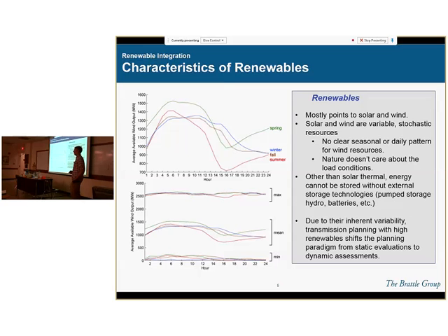And so when we don't have a lot of wind, the load shapes and the load we face are relatively predictable, and we know they have some diurnal pattern, so we can schedule resources and be fairly well assured that we'll have enough ramping capability to meet that load. But when you have stochastic resources like wind, and now you're trying to meet the net load and not the total load, then the ramps may turn out to be much greater than you thought, and if you don't have enough rampability in your generation fleet, you may have loss of load events or something similar.